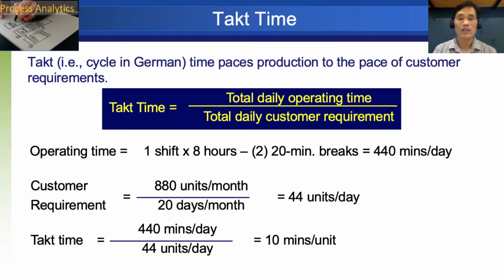Takt time is one of the primary process metrics. Takt time is the amount of time an item or service needs to be completed if a customer's on-time delivery deadline is to be met. The amount of time between one part being completed and the next part being completed must be the same as or less than the takt time. Or we can assume that the parts will not be produced per the customer's schedule.